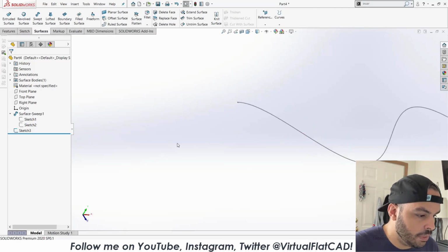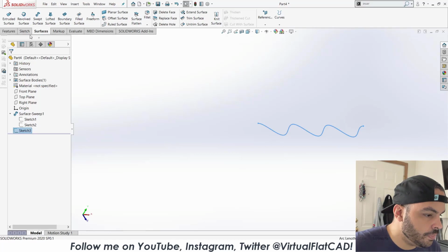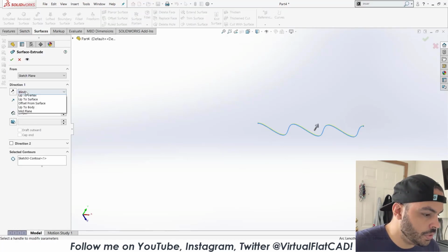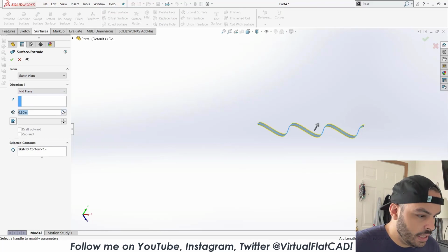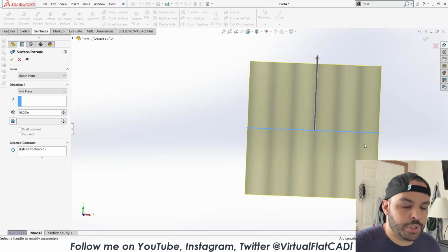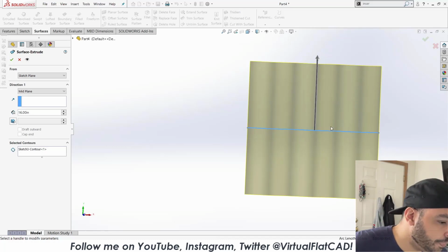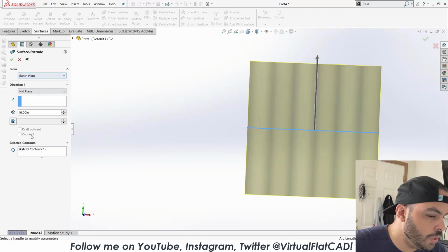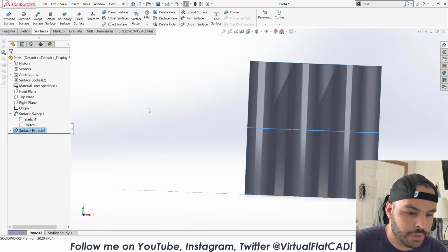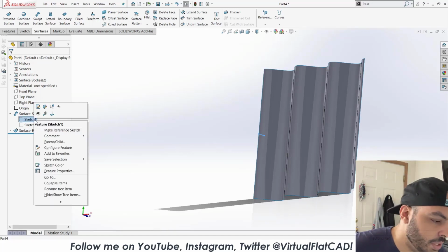We're going to hide that. We'll come back to sketch one later. But with this, we can extrude this as a surface. So we're going to start it off really thin, and make this pretty large. You can have a square shaped flag, but using other surface tools, I'm actually going to trim this down to be the final shape of our flag. So I've extruded this to an arbitrarily large value. There you go. It's kind of like a square, and I might be able to even give you a little preview of what the waving animation would look like.